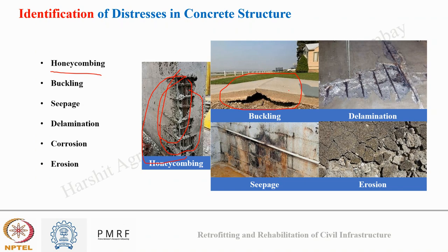There can be several reasons behind seepage in concrete, like poor graded aggregate being used, overdose of admixture, deviation from designated design, improper concrete placement, impurities in aggregate, all can be responsible for water leakage in concrete. And in the images you can see one of the concrete wall showing damp patches of water due to seepage. Okay.